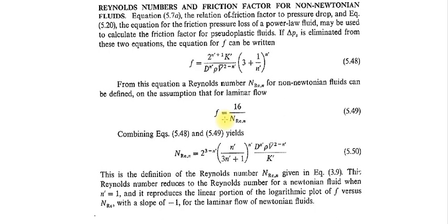So here also, for laminar flow, it is calculated as f equal to 16 by NRE, where the prime or subscript N is used for the non-Newtonian fluid, and this Reynolds number can be calculated by this formula, where this n is the factor used in the power law. If you remember the power law, you have the shear rate to the power n.